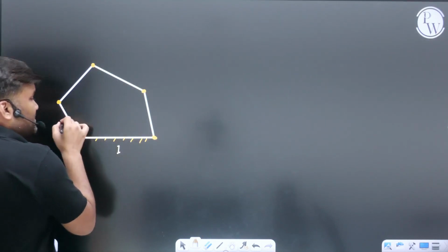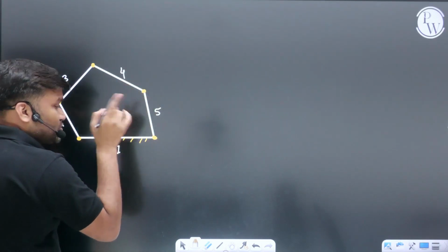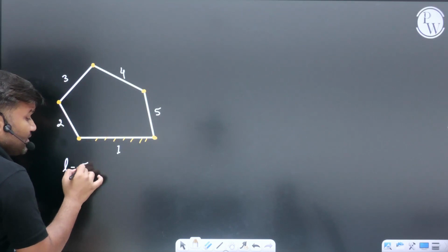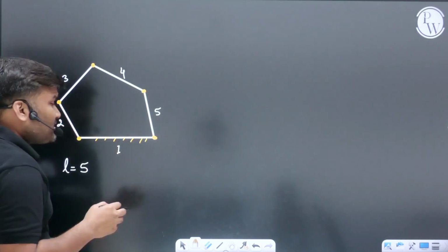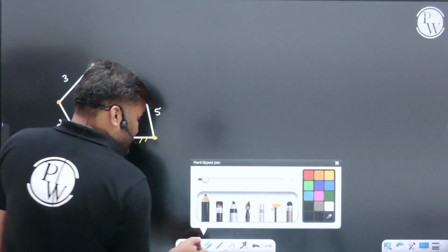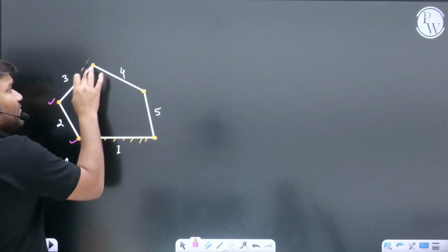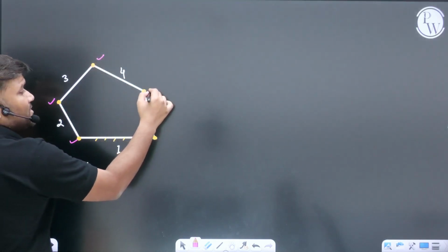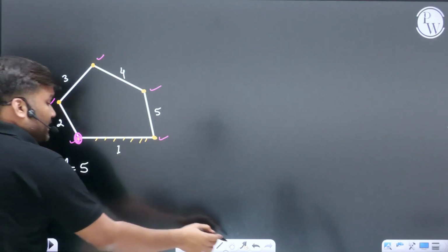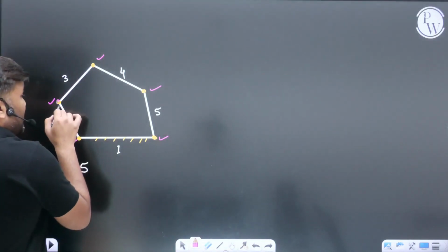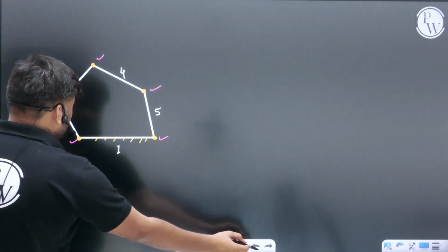This is link number 1. This is link number 2, and this is link number 3. This is link number 4. This is link number 5. So how many total links are there, beta? 5 links are there. How many lower pairs or binary joints are there? Sir, one lower pair is this, one is this, a turning pair, na beta? One is this, one is this, one is this. Each is a pair with 1 degree of freedom. Clear?